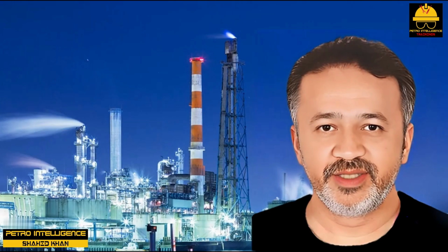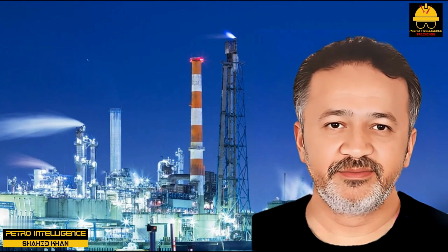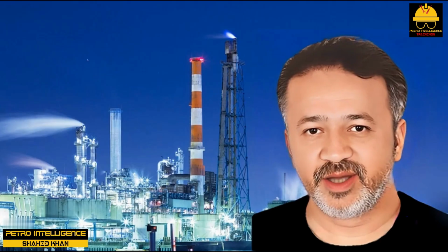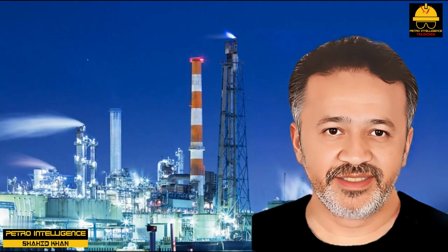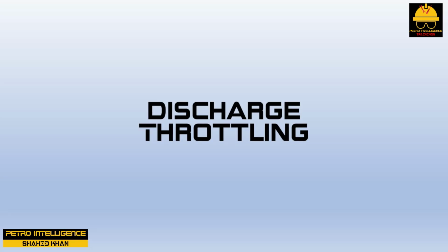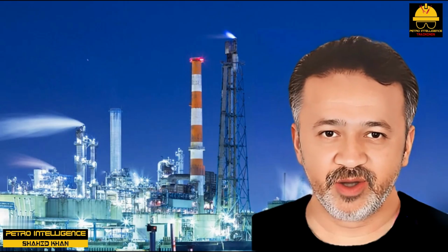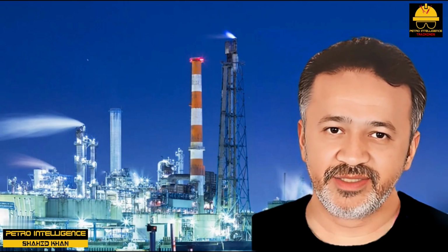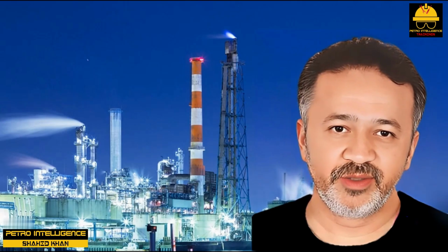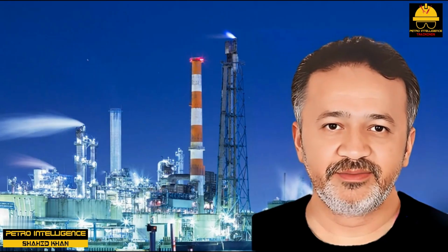Spillback. Spillback bypasses the compressor discharge gas back to the compressor suction. This is a relatively energy-inefficient way to increase the evaporator temperature. Spillback is discussed in another lecture on centrifugal compressors and surge. Discharge throttling. Discharge throttling is also an energy-inefficient way to control the evaporator temperature. Even worse, if we are working with a centrifugal compressor, discharge throttling may cause the compressor to surge.